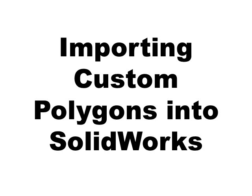Last subject here is importing a custom polygon into SolidWorks. So very often in electromagnetics, we design the shape of something and it's crazy, but we want to precisely place those points and then read it into SolidWorks and extrude that. For whatever reason, SolidWorks does not provide the ability to do that.